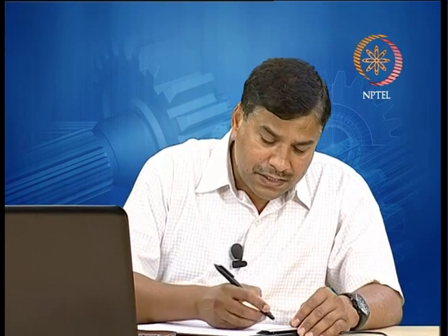Further, sometimes the lower level of the welding current is selected intentionally, so that we can have the desired limited flowability of the weld metal to avoid the falling tendency of the weld metal in odd position welding processes like vertical or overhead welding or the horizontal welding process. So, to see this in detail, the selection of the welding current in the shielded metal arc welding process, we need to see this diagram.